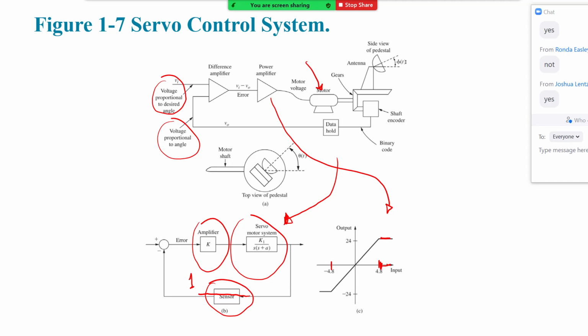But you also realize that if I'm deploying this system, I might be behaving most of the time within the linear region, but during a transient response I might be saturating the amplifier. Make sense? Now this might be acceptable, it might not be acceptable, but again, that's why we need this iteration process.